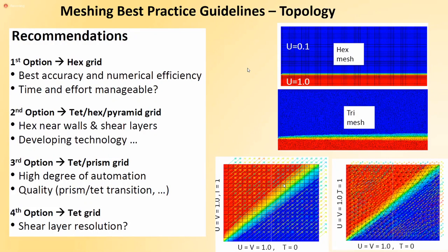So when the flow is curvy and very sophisticated, it turns and revolves, then you'd rather use polyhedra. If I had a helicopter, then usually what I do is use an inner mesh where the flow has really large rotation, with polyhedra, and polyhex core only outside. So I'll split the mesh and connect it, or something like that.